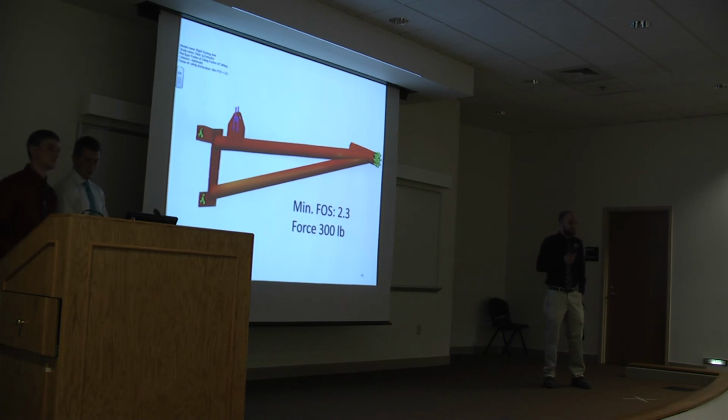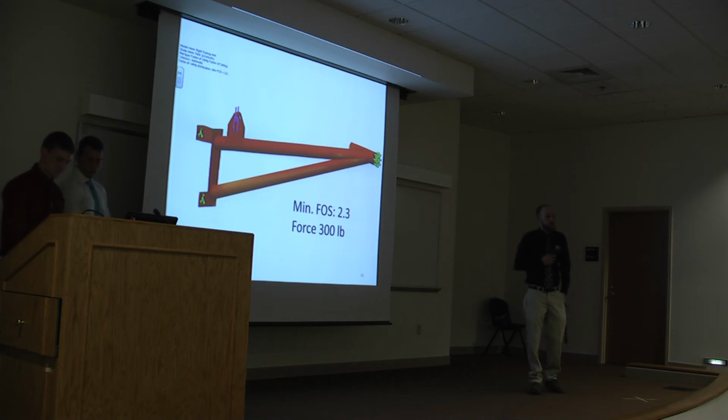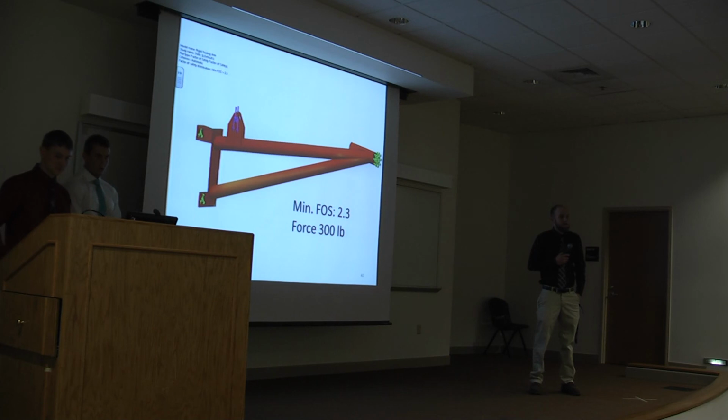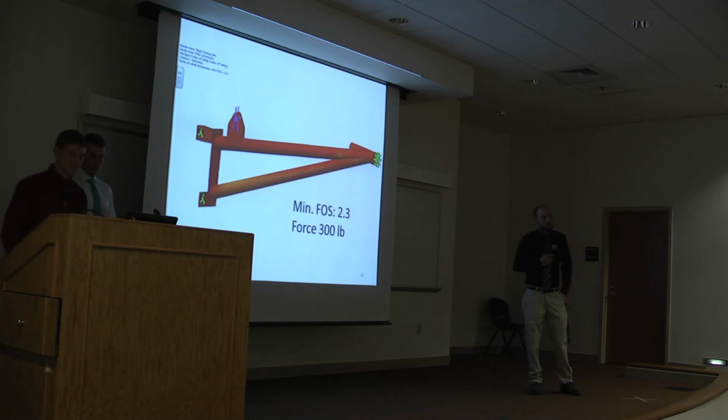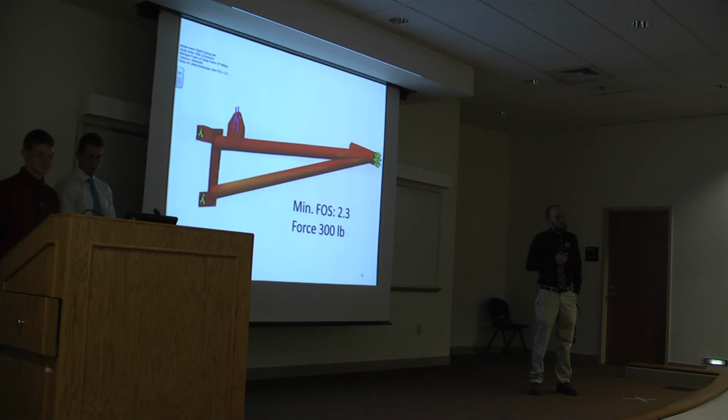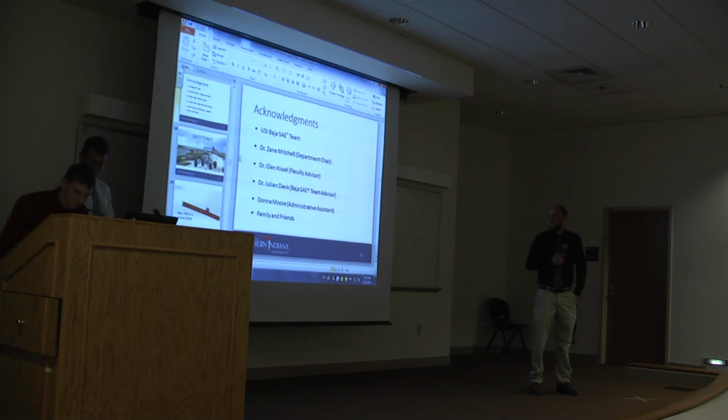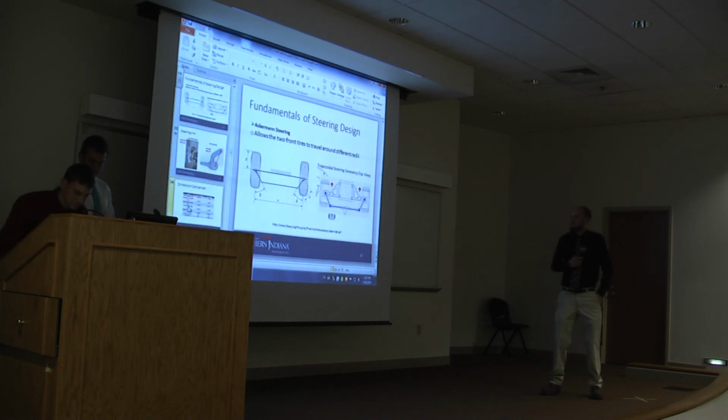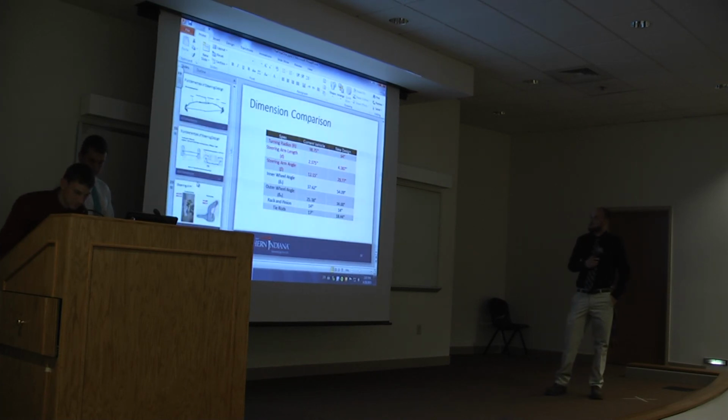Good, thanks. I've got a question on your design of the trailing arms. I noticed they came out at an angle and you've got the short, straight piece to tie in perpendicular to the frame. Why not just put your mount on the frame at an angle? I feel like you have a lot of torque force, the way that's mounted currently with your mount being in a straight line, but your trailing arm coming off at an angle. I feel like any kind of twisting motion is going to put a lot of strain on those mounts.